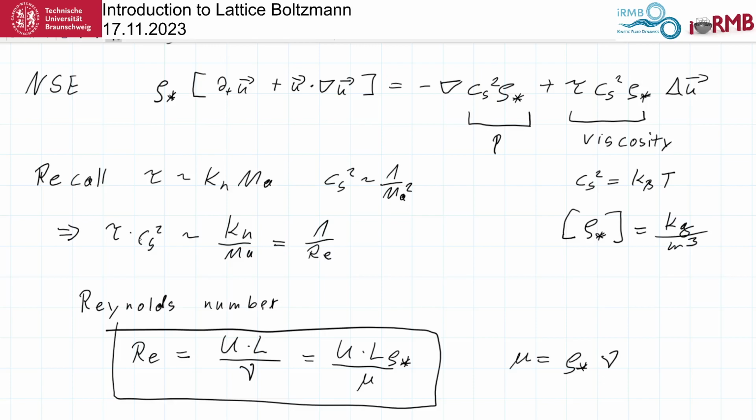So the dynamic viscosity is independent of the density because it depends on the density in two opposing ways. It has the density inside, and it has the mean free time inside, and the two cancel each other out, such that the dynamic viscosity becomes independent of the density, while the kinematic viscosity is dependent on density. This is why usually, if you ask about the viscosity, you ask about the dynamic viscosity. Yes, it's easier to deal with.